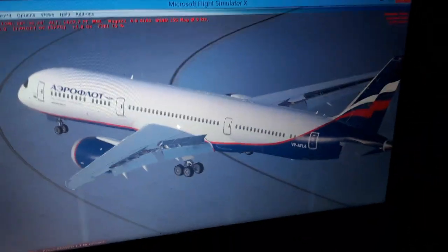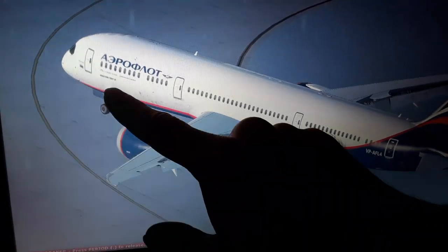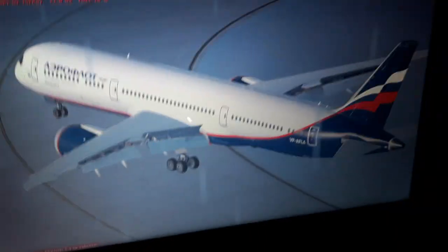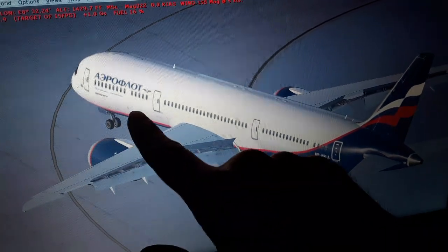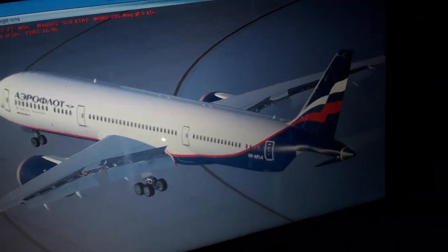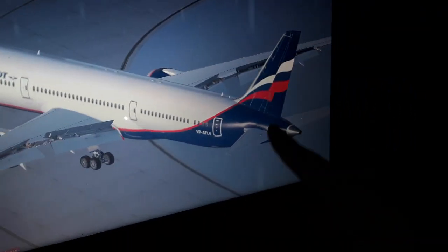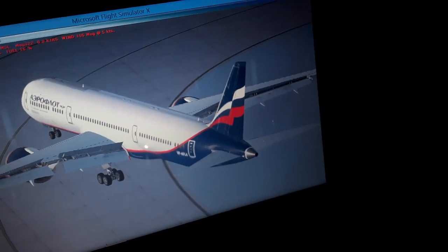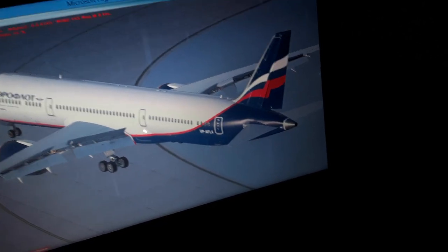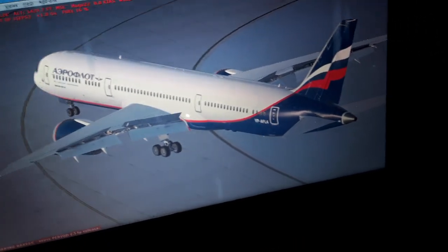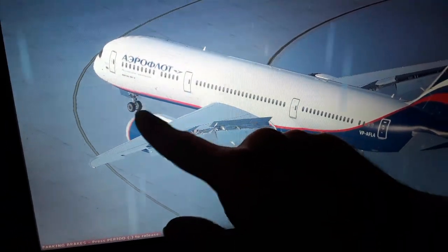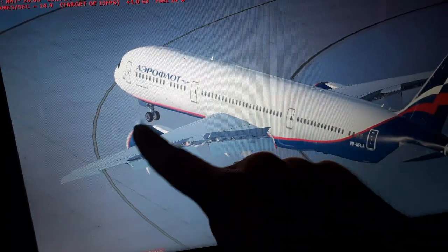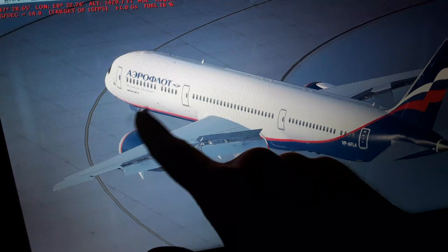So we have the rudder. Here you can see we have the nose wheel. I told you we control with the rudder pedals or the nose wheel steering. It deflects 76 degrees either left or right side from 0 up to 45 nautical miles per hour airspeed. Then the rudder becomes aerodynamically effective above 45 nautical miles per hour or 72 kilometers an hour in takeoff, or in landing, inverse. So the computer automatically decreases the forward nose wheel deflection from 76 to 7.6 degrees.